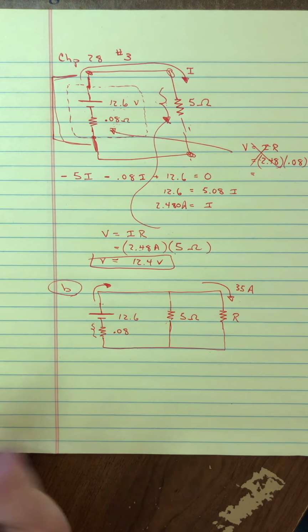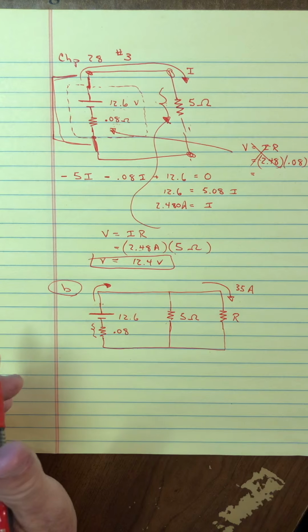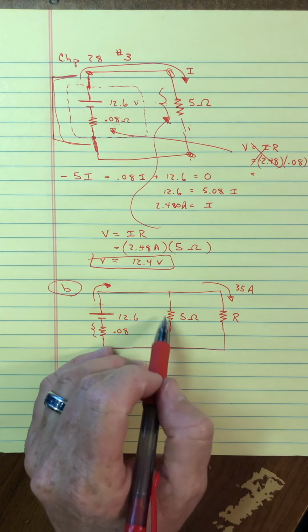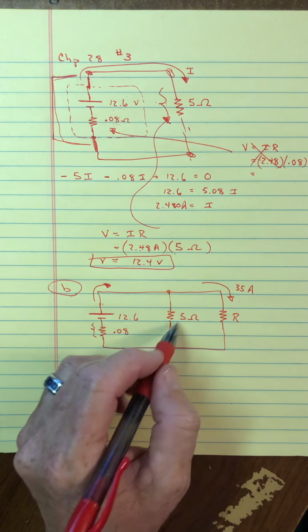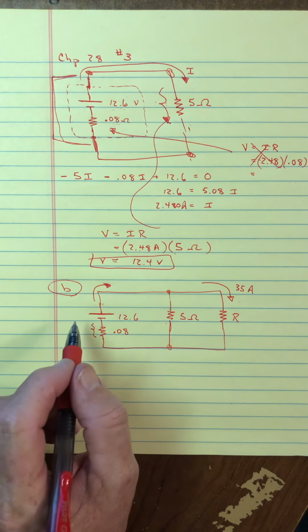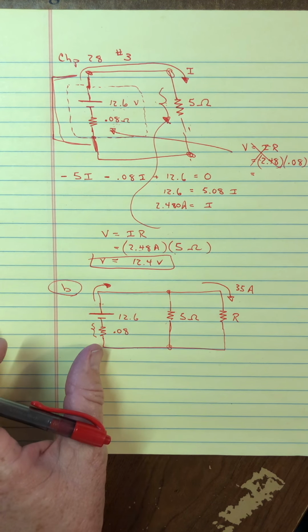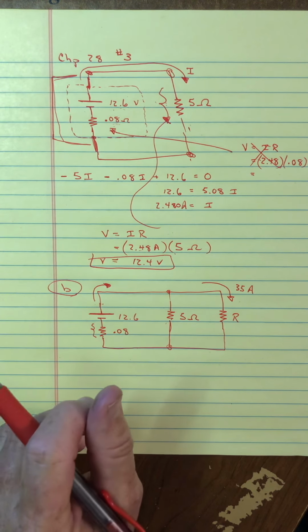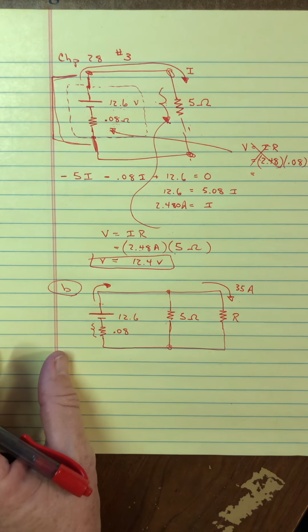Okay? But I would even argue that it's going to be even more complicated, because in addition to that, there's going to be a change in the terminal voltage, which is going to reduce the current in the headlights. That's why if you've ever seen a car start, the headlights will dim down a little bit, or starting a dryer in your garage. I often see this.